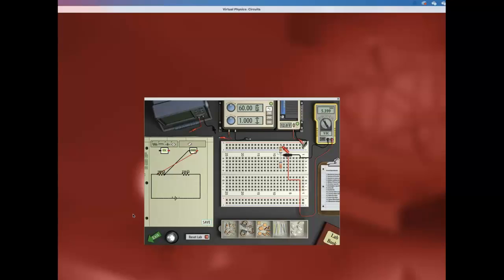You will take only the snip for part A and measure the potential difference across points A and C. And this one here, we call it VAC. And the software will not allow you to put the meter's terminals across the power supply. Let me see here. This is the reason why you will do maybe something like this.